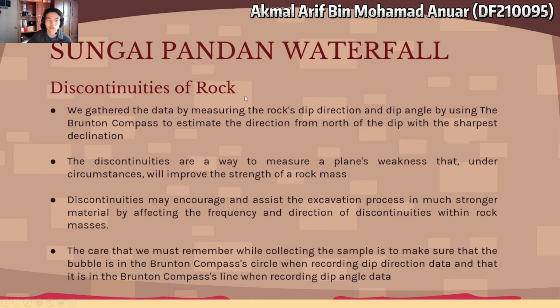So we start at Sungai Pandan Waterfall, with the discontinuities of rock. We gathered the data by measuring the rock's dip direction and dip angle by using the Brunton compass to estimate the direction from north of the dip with the sharpest declination.